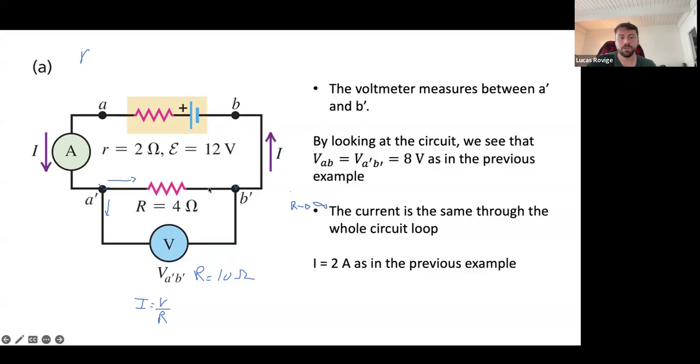So you could pretty quickly get the amount of current going through there and through there. And so you now see that you are messing with your system, because you're drawing some current from your system into your voltmeter, and you're preventing this current from going into your system.